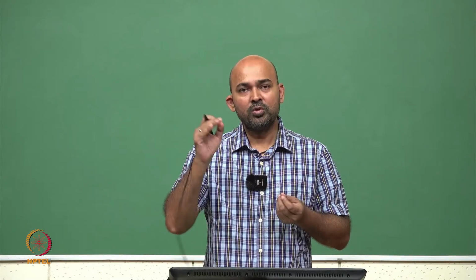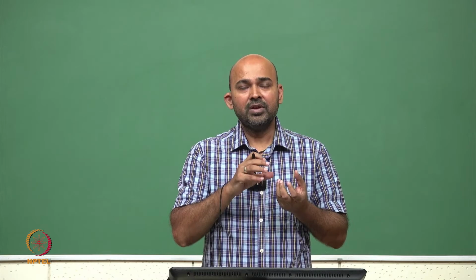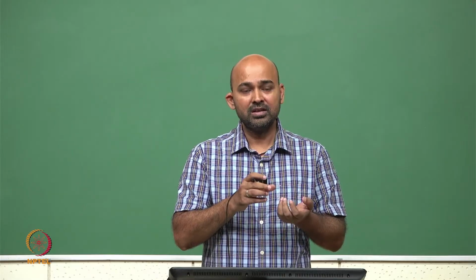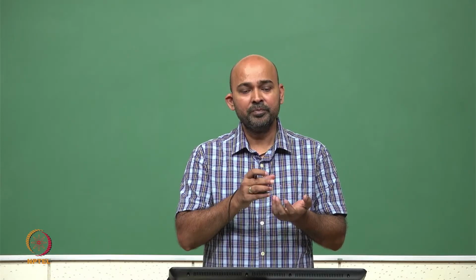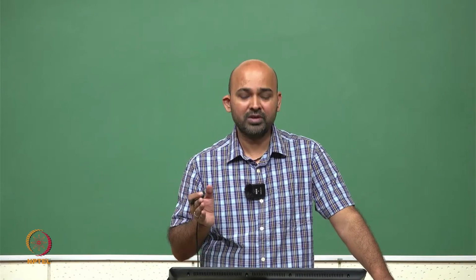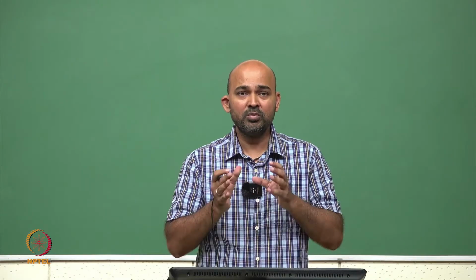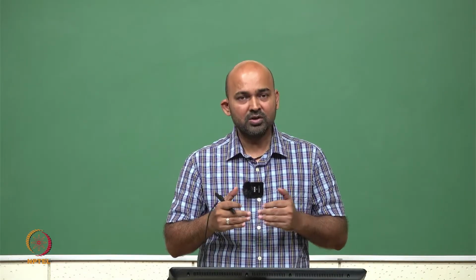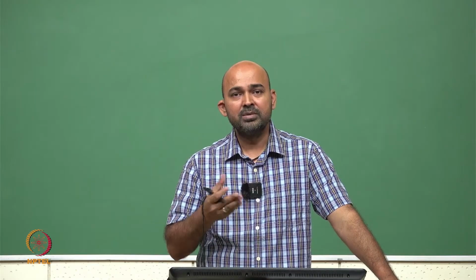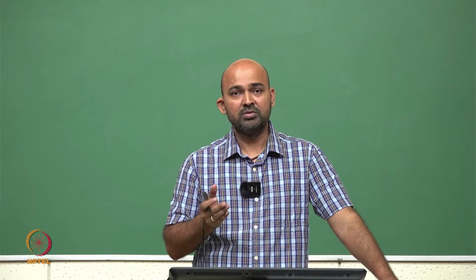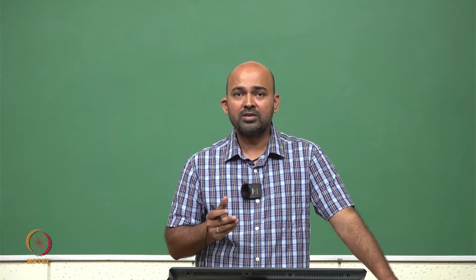and the result of this NAND gate, the transition from low to high and high to low, will be very much accurate, very close to the actual silicon. When we fabricate this on the silicon, the simulated output will be very much similar to the fabricated circuit. However, for a large number of transistors, large number of gates, SPICE is impractical. It will take too much time and too much memory, so it is not practical to use it. For something like 10,000 gates, it may take even days to simulate. So that is why we need some CAD softwares.